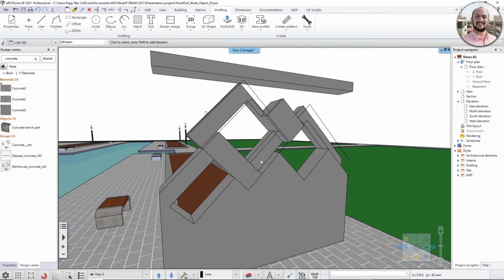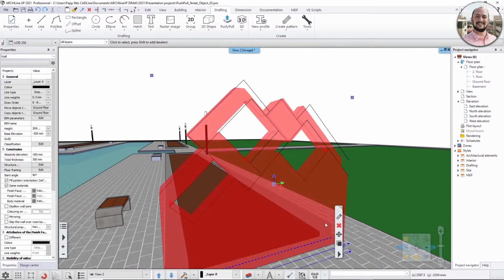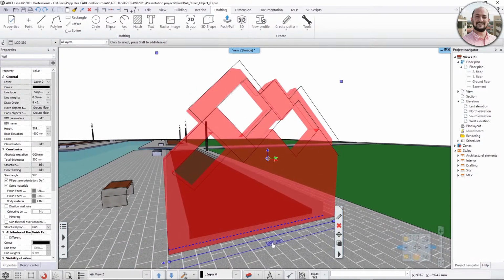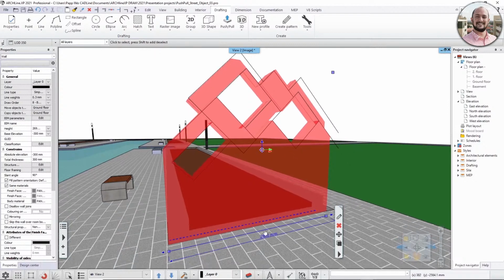So it will be kept with the wall, and the same happens if you make the wall a little bit smaller, shorter or longer. Let me try to change this to 2800 or something like that. In that case, the rest of the model here will be chopped off. And I can do the same thing here. Let's just make it 2600 from the left hand side.